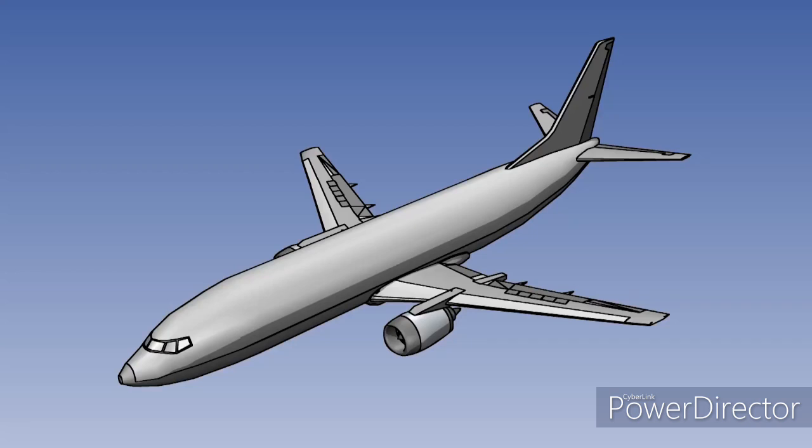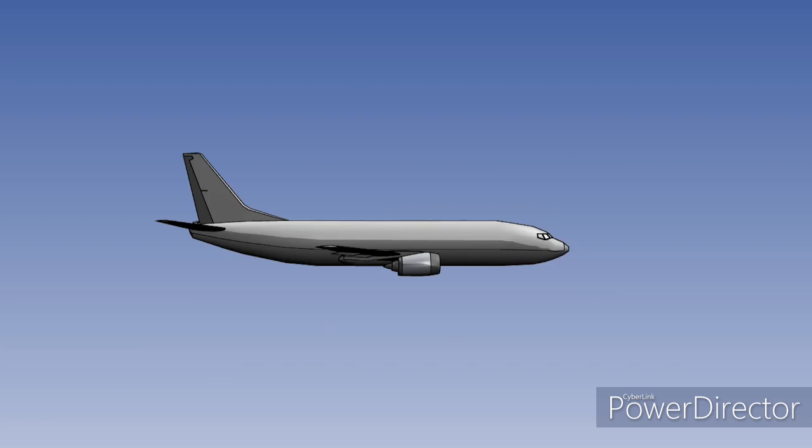In this series of lessons on flight mechanics, you'll be studying the forces acting on an aircraft in flight and the response of the aircraft to those forces. For an aircraft to be in steady, unaccelerated flight, the following conditions must exist. Forces acting downwards must exactly balance the forces acting upwards, and the forces acting backwards must exactly balance the forces acting forwards. In addition, the sum of all moments must be zero. When all these conditions are met, the aircraft is in a state of equilibrium.